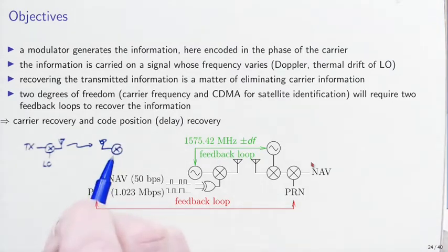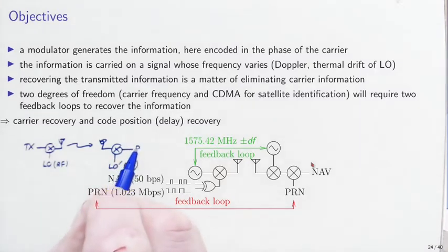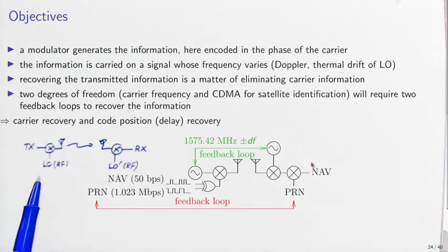So this is only an intermediate step, this frequency transposition over the carrier radio frequency. So this is an RF signal, this is an RF signal, if only to share spectrum and to match antenna dimension with the application. But at the end of the day, what we wish is to recover the information. So the objective of demodulation is to compensate for any offset between the transmitter and receiver local oscillators. In the case of